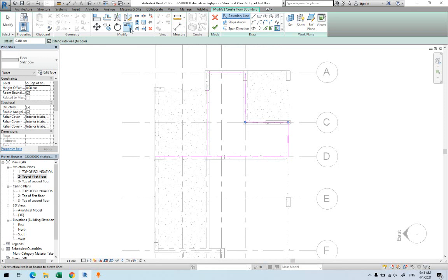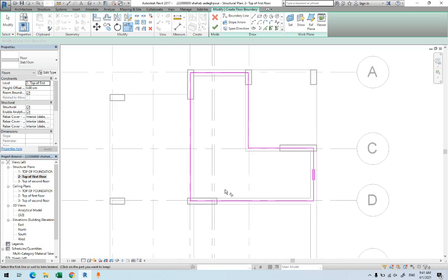So what we'll do, we're going to click on this icon, which is trim and extend. Click on the lines to connect them together. Make sure everything is connected here. It's already connected. This one with this one to be connected. Now make sure everything is connected there. You have the slab, and now there is no opening there. I'll just press finish here.